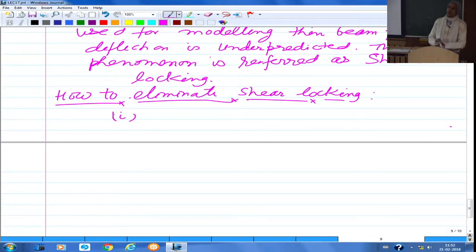So if we interpolate v one order higher than theta z, say theta z is interpolated using a linear polynomial and v is interpolated as a quadratic polynomial, then dv by dx will also have a constant term and a linear term. Theta z already has a constant term and a linear term. So again the resulting constant would have both v and theta z terms, so the constraints would not be inconsistent in that case.